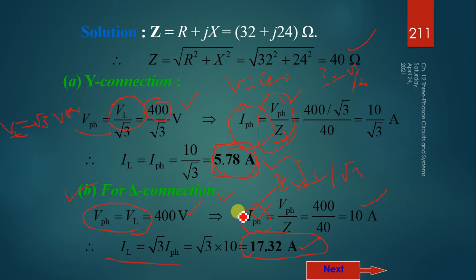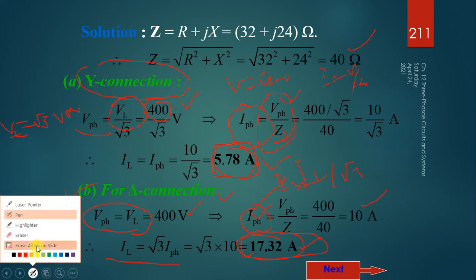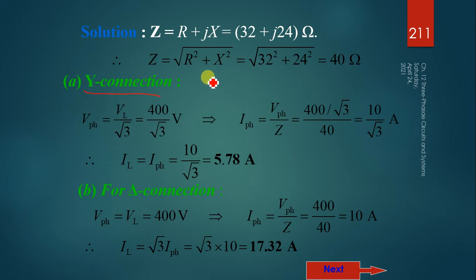Delta connection. Here in delta, amperage is more, right? Similarly, which type of connection is suitable when you require two types of voltages? Y connection or star connection, right? Star connection is suitable when you require low current at the beginning and voltage to be of two types of voltages. Similarly, delta connection is suitable for high amperage when the current requirement is very high at the beginning. But the problem is you don't have two voltages split up here. You don't get multiple voltages here, right?